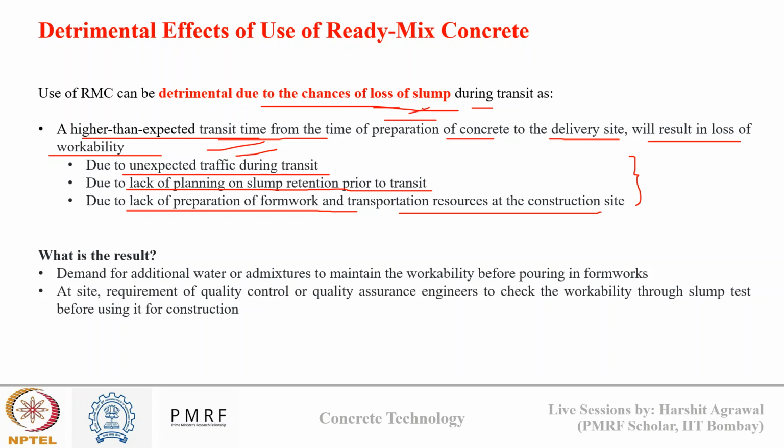And if we record loss in slump, when we are pouring our ready mix concrete inside the formwork, it won't compact properly and it will give me a compactability issue in the concrete, which may not yield the performance that I want from concrete. So though ready mix concrete has several advantages, the loss of slump can be a disadvantage that can come if the planning is not done properly.